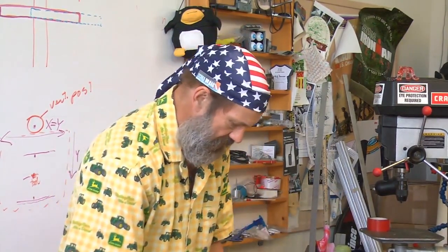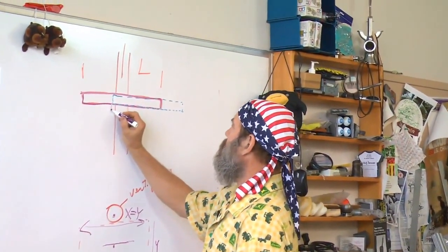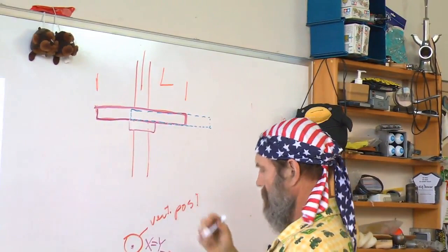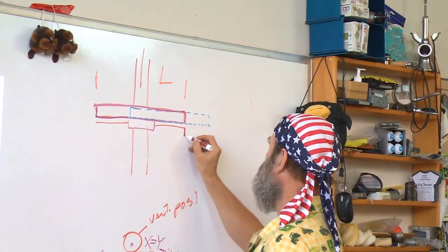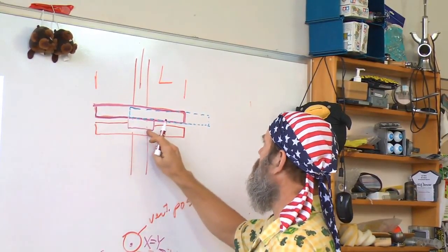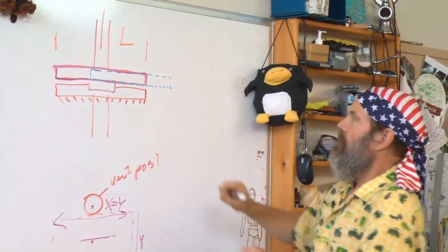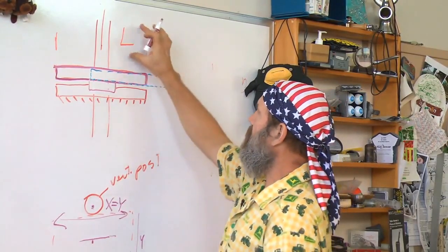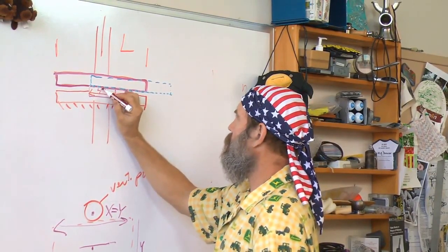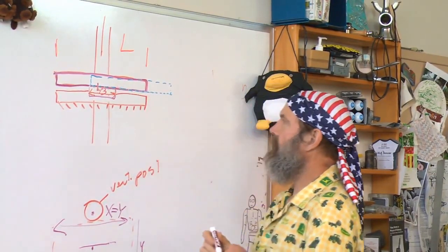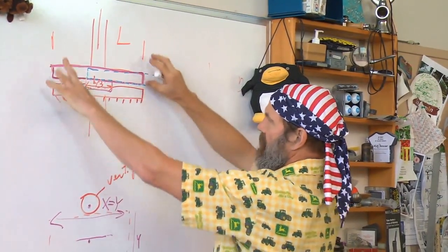If I were to do that, that would mean that, for example, I put a bearing block here and then a rail underneath it, where the rail is fixed to the column. St. Venant tells us if this is L, that this bearing engagement better be at least L over 3. If this table gets much bigger than the spacing on the bearing blocks, then it's going to be too soft.